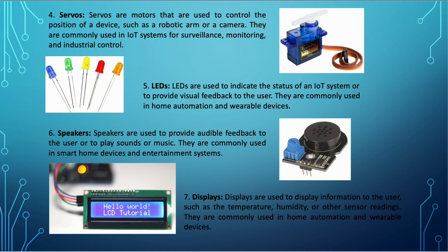Again, when using a servo, things that need to be considered are similar to the motors itself. The capacity, the torque, the energy which is needed. If you are going to use this in a small IoT device, the size of the servo and so on, there are a lot of parameters to consider when designing an IoT device.